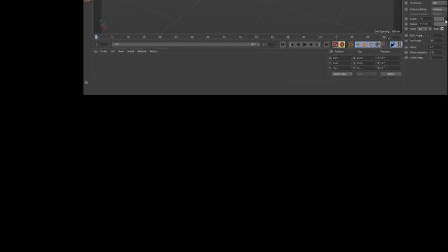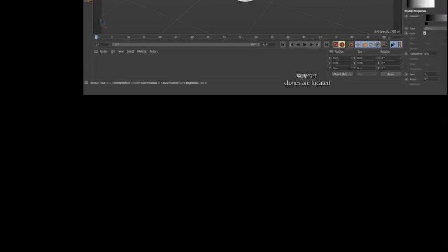And now, for it to work, go to the Parameter tab and increase the value to 100% of the modified clone parameter. Set up the cloner a bit to show all kinds of copies. I return to the gradient, changing it. We can see how the clones are located.